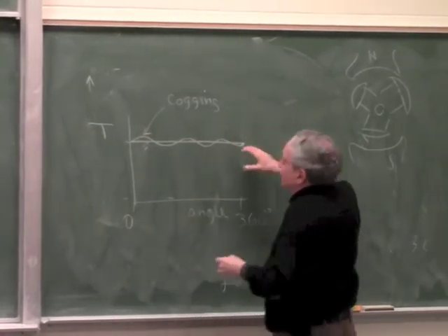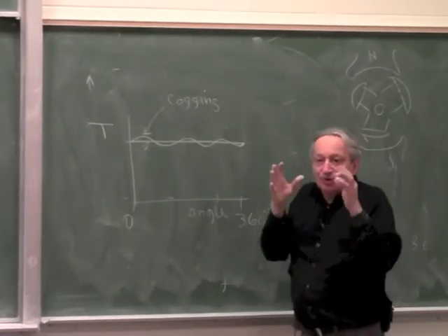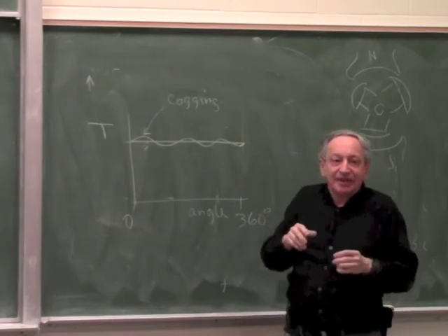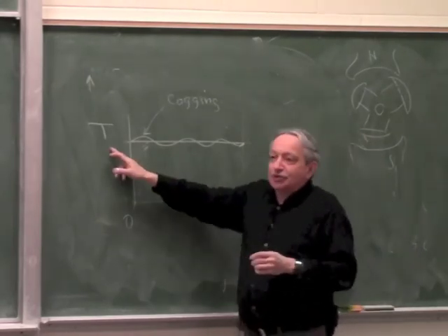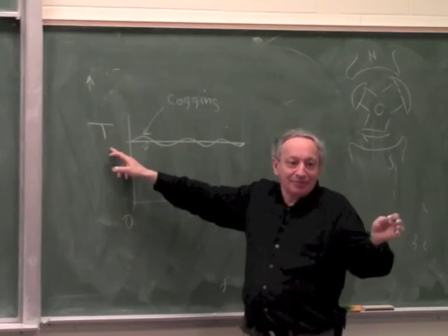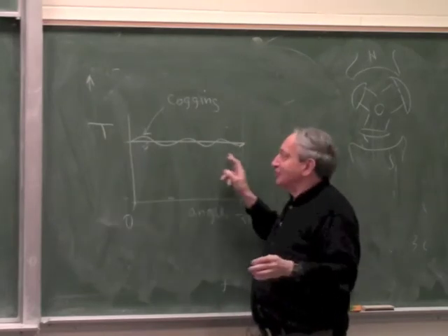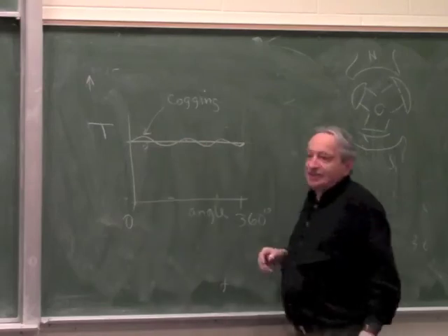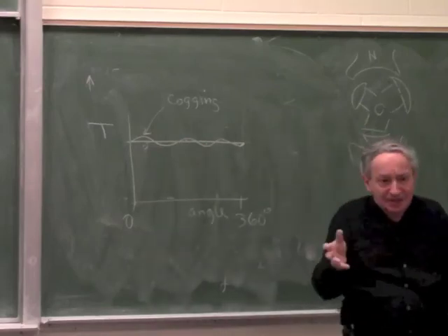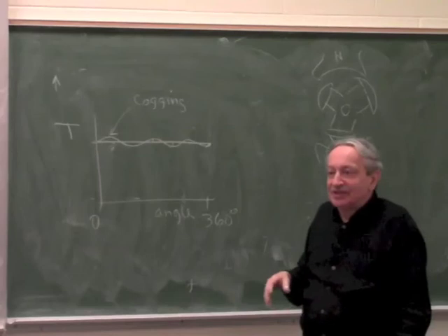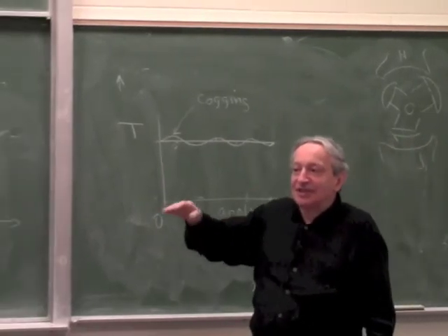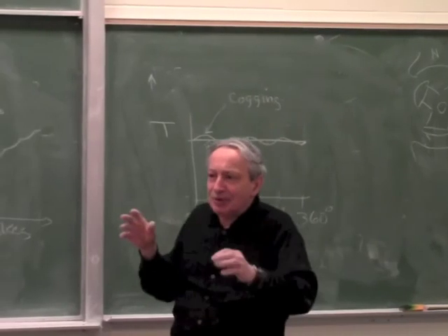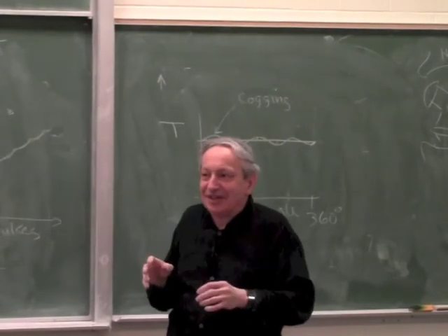If we draw the servo, the block called plant, or the block called actuator, doesn't have a constant conversion of so many torque per amp. The conversion depends on position. So if this varies 10%, and that's typically what it is in a regular motor, it is the same as the gain fluctuating 10%, and that's not so good, because in some servos we like to make a perfect model and we need to know the exact gain.